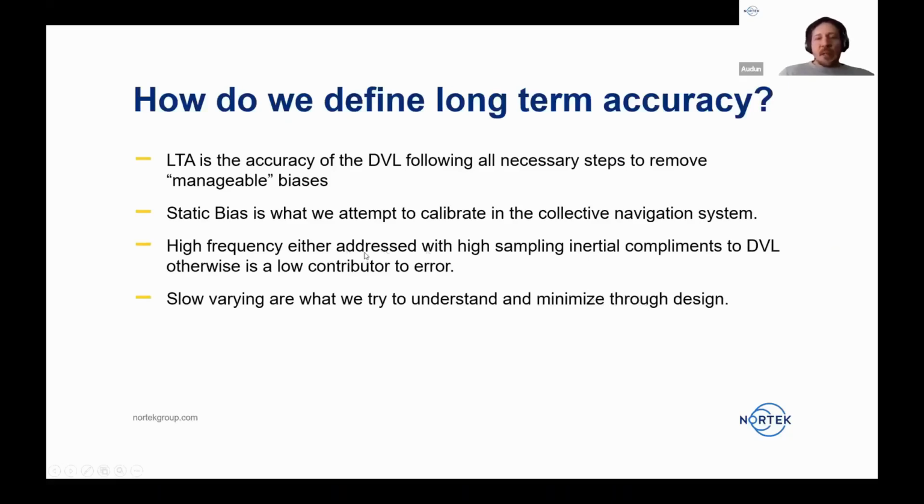Also, I should say that at the high end, if you were interested in the more high bandwidth, quicker motions, then it's good to use the DVL with an INS, which has inertial sensors that have very, very low noise, so they can measure variations on these short time scales, but they'll drift off really quickly. So the DVL is necessary to pull in this drift. So that's what the long-term accuracy is, really the bottom line for the navigation, also in an INS.